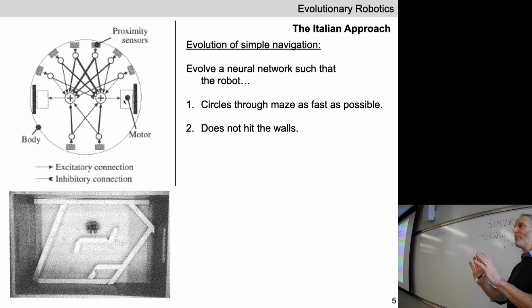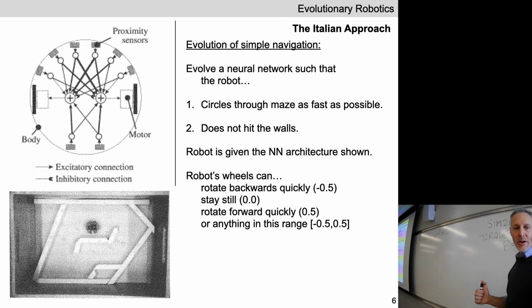So they're kind of building in collision avoidance already. They're giving it the basic idea. Exactly how quickly and how much it turns away is going to be dictated by the magnitudes of these synaptic weights. What are the ipsilateral, same side excitatory connections? What are they doing? They're then exciting that one motor to speed up even more and turn faster. They're adding to collision avoidance, right? So if there's more proximity front left, turn the left wheel more. Okay. So there's the neural network architecture over here.